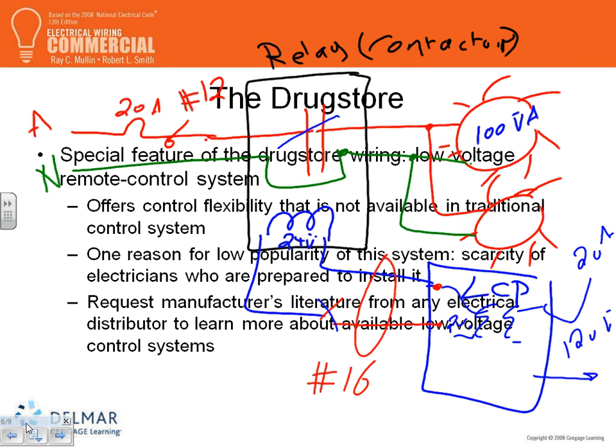You can override them. There are so many ways, and I really don't want to get into it, but the best lighting design, at least from my point of view, guys, is not where you see that coil here, Brad. I put the coil and the contact separate from the panel. Most likely, a good design will take the whole deal and put it right inside the panel. So now your coils and contacts are all right in the panel. You have full, complete control over the coils, and then you bring your switches. That's what really is the good stuff. You bring the wires. Here's my switch, for example, and my switch is going also to the panel, and my coils are going to the panel.